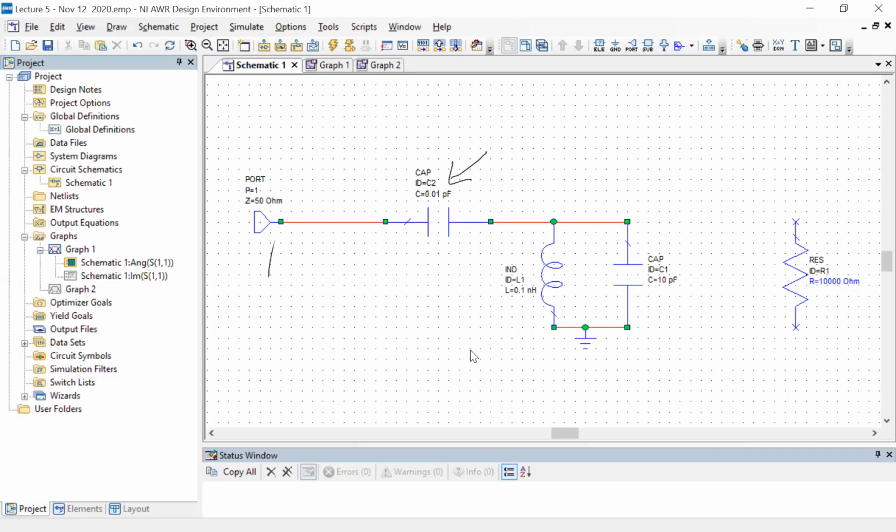One is trying to make higher quality factor resonators, which can have a very sharp resonance. And making small capacitors is also compatible with high frequency operation. It's easier to make smaller capacitors. So this is the very natural and simplest thing to do to control the quality factor of the resonator.